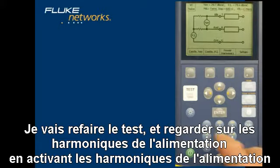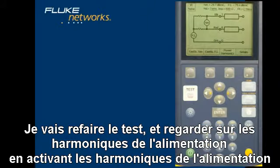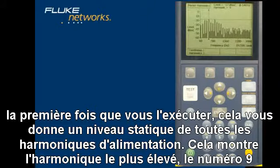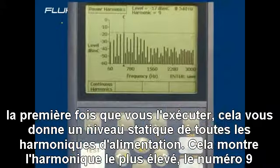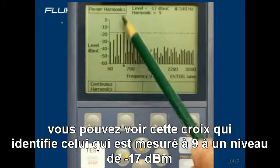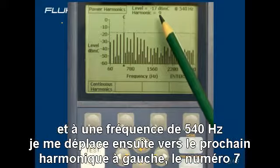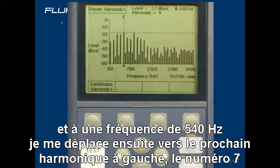This time I'm going to take a look at the power harmonics by hitting the power harmonics button. The first time you run this, it gives you a static level of all the power harmonics. It has highlighted the highest one, which is harmonic number 9. You can see this crosshair identifies the one that it has measured, 9. It is a level of -17. It is harmonic 9, and the frequency is 540 Hertz.